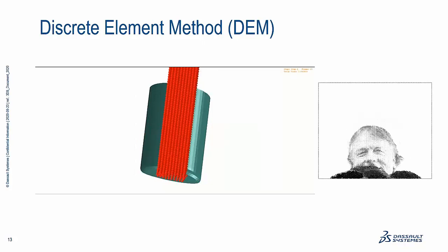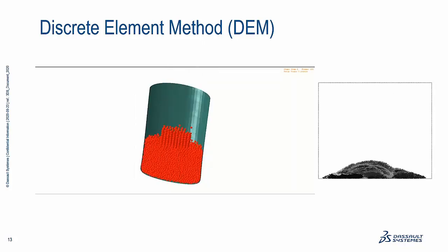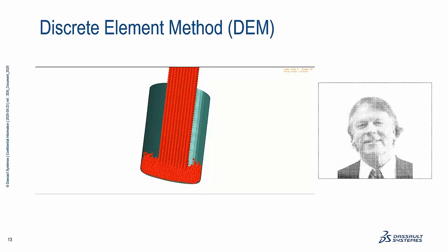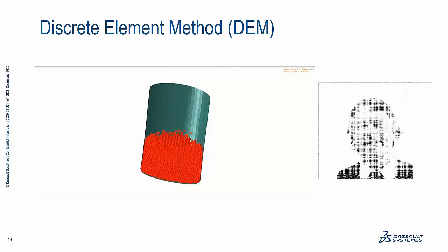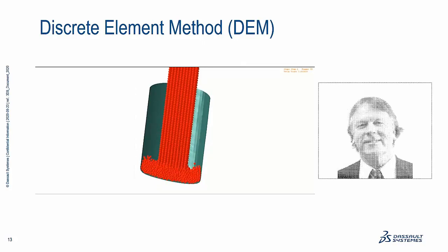The difference being that for the discrete element method, we're not treating these particles as if they're part of a continuum. We're treating these particles, think of them as if they were just rigid billiard balls stacked up on each other and are contacting each other elastically, or they can even have some stickiness and some inelasticity associated with the contact.